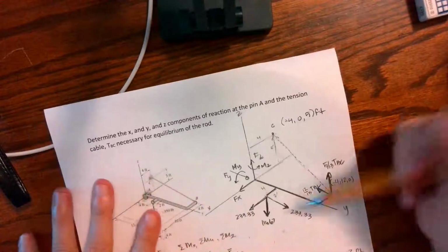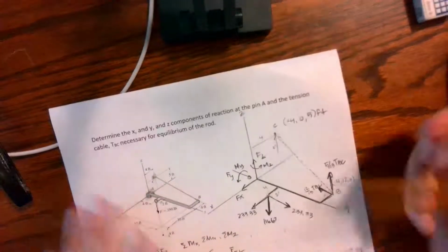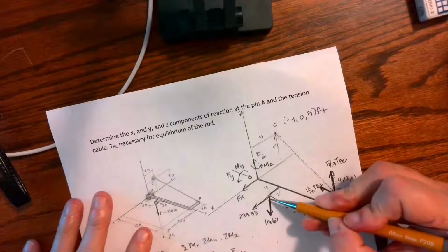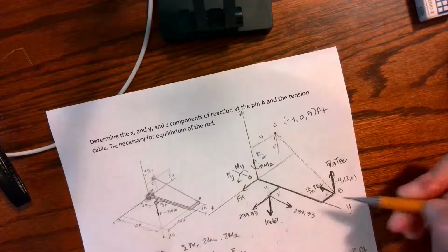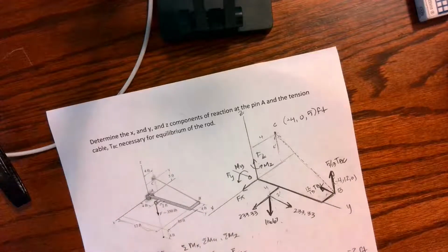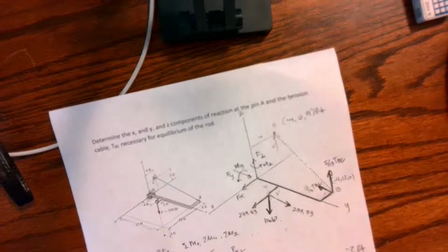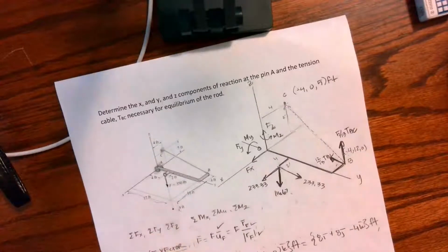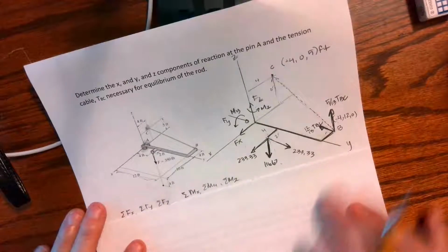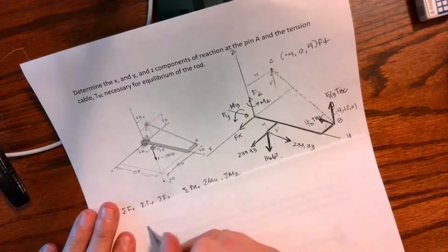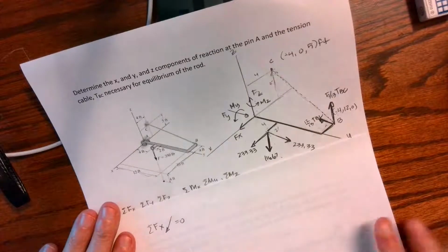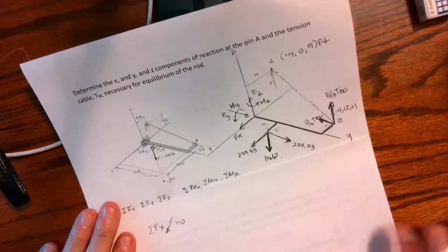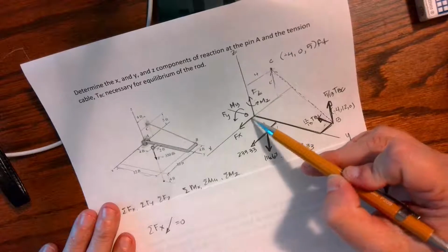So I now have this nice little free body diagram with my unknowns. I have my force vector and my tension cable broke into XYZ components, and I drew them on here in components so that I can just see the moments and forces that are being created. So now we get to do the fun part. Well, I guess that was the fun part, but we're going to start with summing forces in the x direction, positive coming out towards me, sum of Fx equals 0. And I'm going to start here at my unknowns.